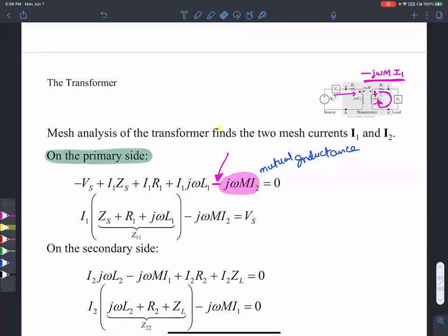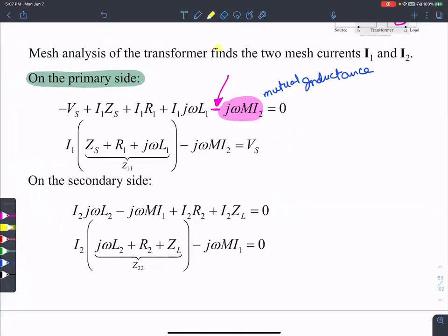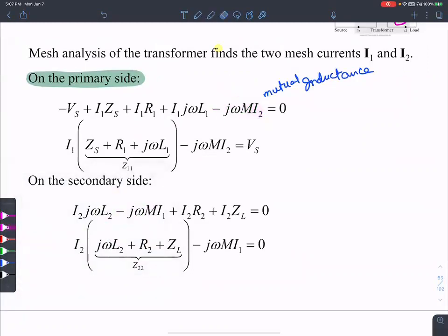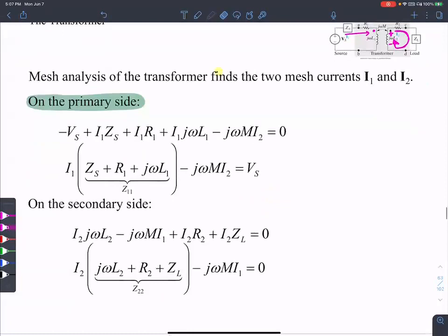Okay, the rest is simply finding the right equations to substitute in. It's just algebraic manipulation at this point. The only thing you want to remember is, when you're setting up the KVL equations, don't forget the mutual inductance term, and it has an associated polarity as well.